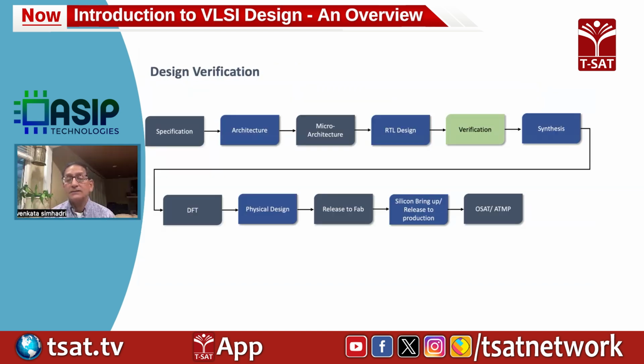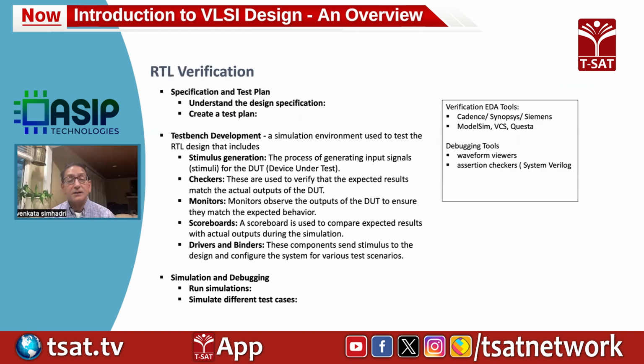So after the RTL design, the next most important thing in the design cycle is verification. Basically, you have to make sure your RTL meets the specification and the functionality of what you're trying to do. So RTL verification starts with specifying the test plan. You have to understand your design specification and create a test plan.